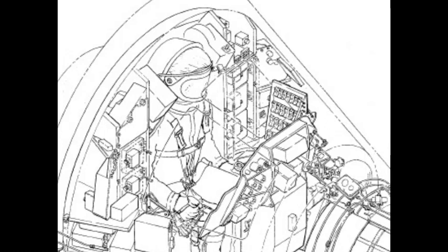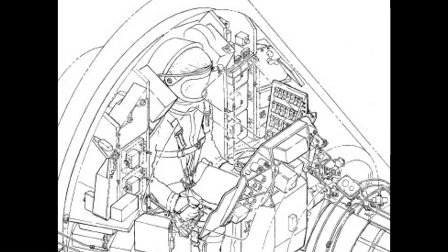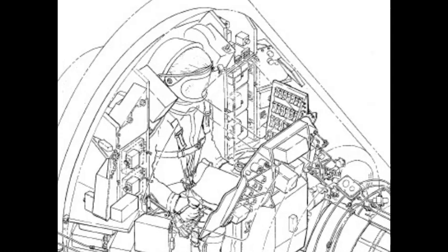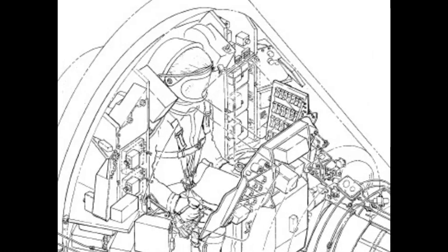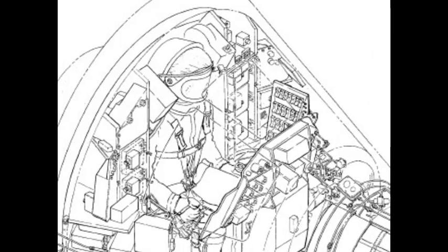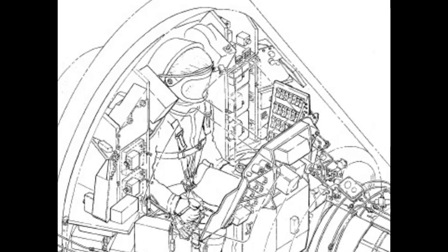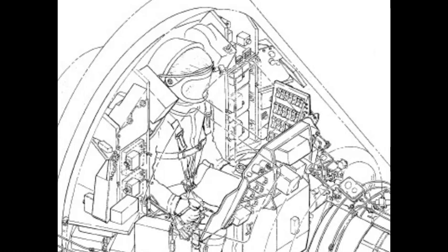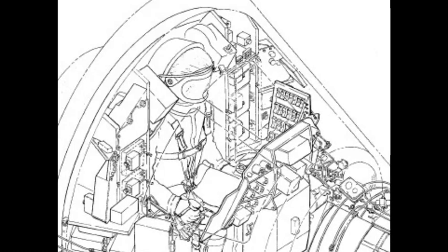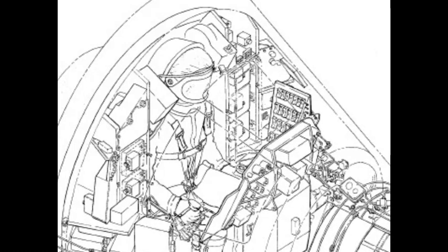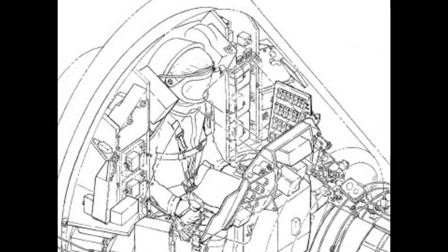In line with the 3 Teflon strips and attached to the antenna fairing shingles are 3 titanium angles. The Teflon strips and the titanium angles prevent damage to the antenna fairing when the escape tower is jettisoned. A steel post, located in the center of the fairing, is the center structure of the fairing.